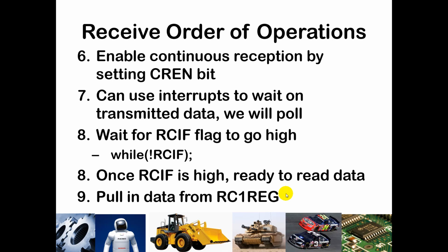You can enable the interrupt if you want to have an interrupt service routine to handle the data, or you can simply poll. And what we will do is simply poll for that data. And then what we will do is wait for the data to come in. And so you see on the screen what we can put there is while (!RCIF);. Exclamation point is short for not.